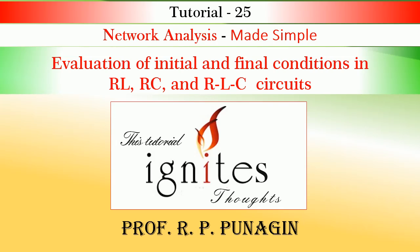We know that whenever the circuits are switched, either by change in supply source or by change in circuit elements, there is a transitional period during which branch currents and voltages across the circuit elements change from their former values to the new values. This transition period is called transients.